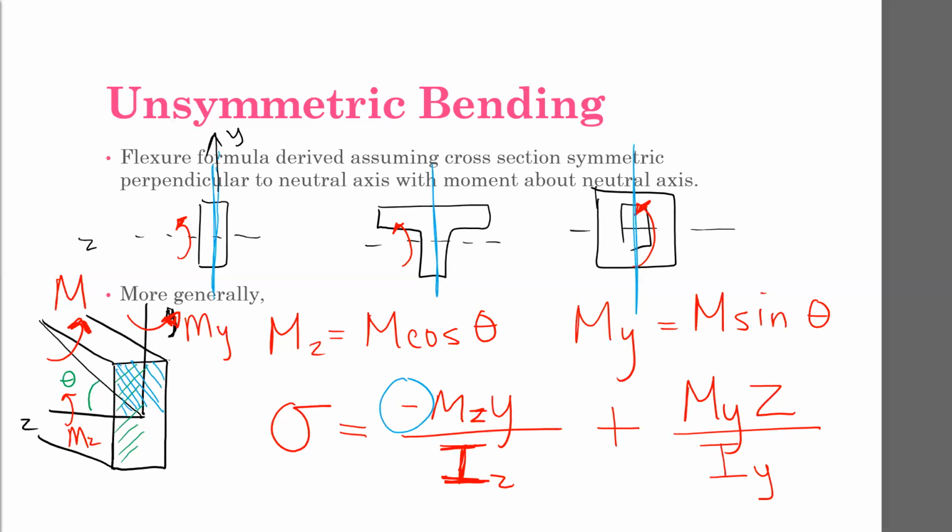And that's typically the way that I do it, is typically my math is a positive moment and a positive y regardless of which way I'm going. And then I think to myself, should this location be extending or should this location be contracting? And then I let that guide whether my final answer has a positive or a negative sign. But whichever way you do it is fine. One's more formulaic, one's more intuitive.